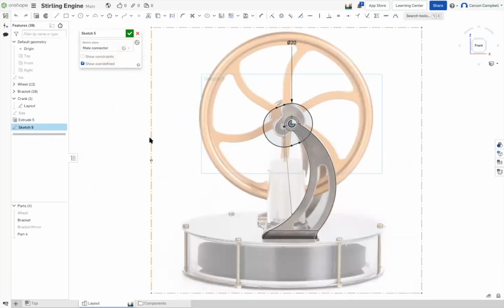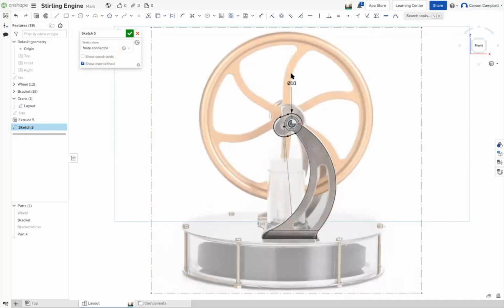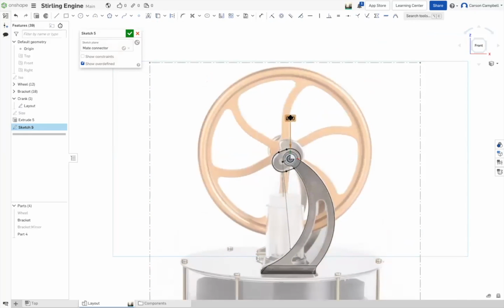Change 20 such that it matches the diameter of the little piece of that counterbalance. Hit the down arrow, double click it, hit the down arrow key one more time, hit the N key. Double click that, hit the down arrow one more. That, I like that one. Accept that. I need for you to now go back to the slot, but I'm going to do an offset.